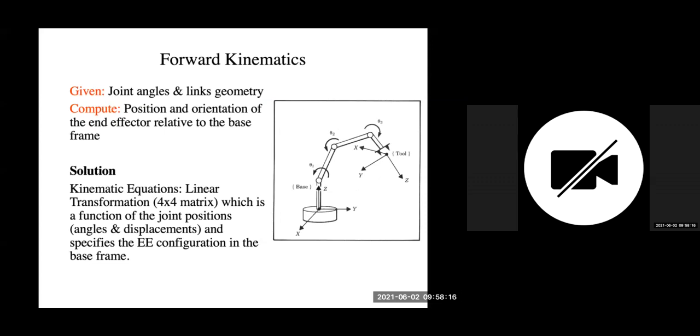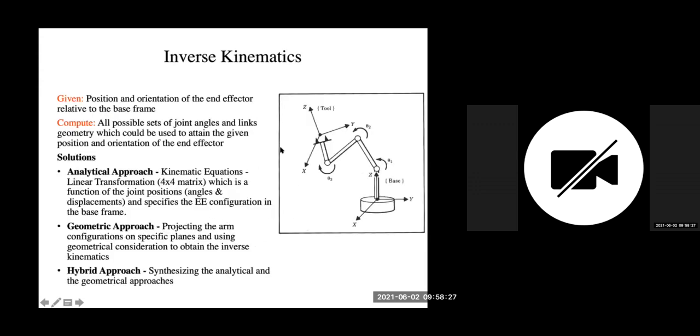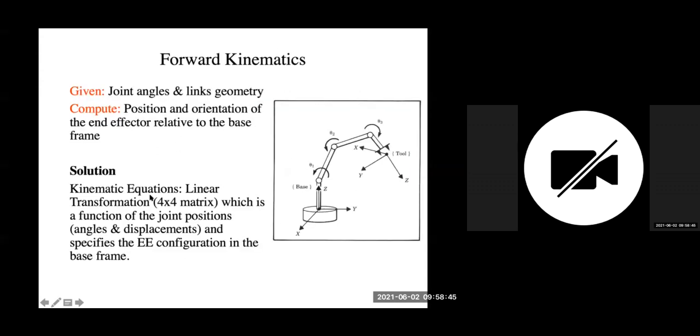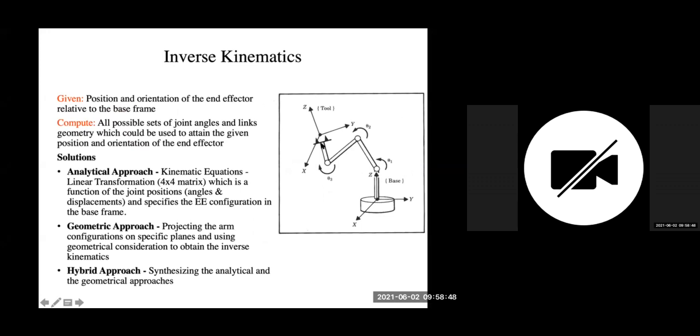to do. The forward kinematics is trying to say, hey, if I give this angle data, what is my ending position and the orientation of the end effector, okay? The inverse kinematics is, hey, I want to reach a certain location, a position at a certain orientation. So how would I pick the angles over here, okay? That's called inverse. Inverse typically can be a little more challenging, because this one you have a unique solution you can figure out, while the other one, inverse, you may have multiple solutions associated with one particular configuration of the end effector, okay? So that's for the robotic arm, okay?